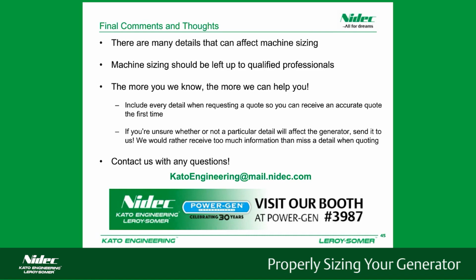Thank you so much. Okay, the next question we have is, is SKVA the same as KVAR? No, they're quite different. SKVA is the starting KVA on a motor, and KVAR is the reactive load put on a generator from an inductive source or a capacitive source. Okay, thank you. That's great.